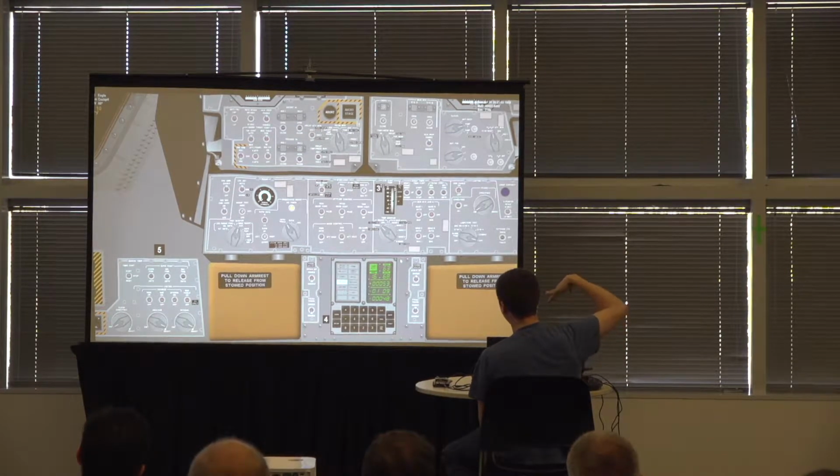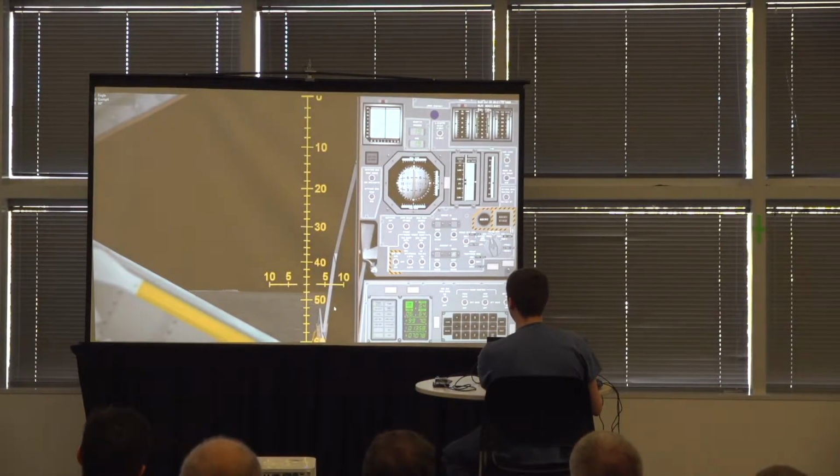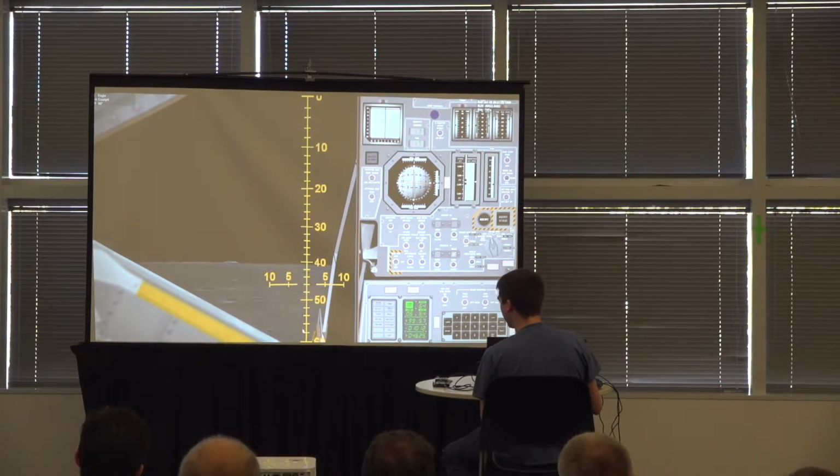So at this point, the lunar module is going to pitch forward so we can see out the window where our landing site is for the first time. So there's program 64. If I look out the window, we can now see our landing site. So we are now looking at noun 64. The most interesting number here is the top right. This 59 is an angle, and if I look at the markings on the window, which is called the landing point designator, at that angle, so 57 degrees is right here, I can see where the AGC is trying to take me.